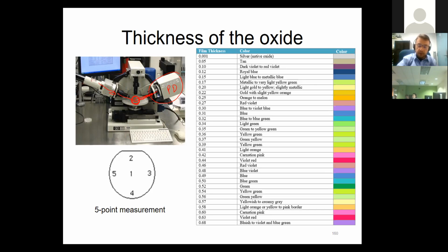and the photodetector will do some reverse engineering to sort out the exact thickness. There are other ellipsometers where you don't have to do this, but you might have to enter an initial estimate, a guess, as the user. So you put your wafer next to charts like this, and then you try to associate the color that you see coming from the wafer with these color charts, and then you say, okay, so it might be 0.34 micrometers. So I'm just going to enter that guess and then let the ellipsometer take care. If it is in this vicinity, it will give you the result in angstrom level. That's how powerful ellipsometers are.